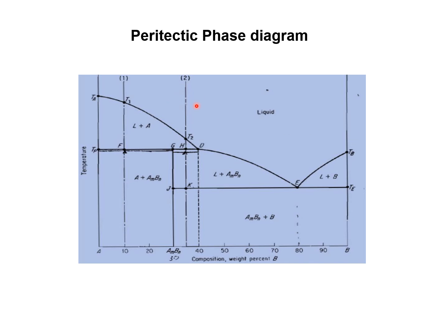Here this region is entirely liquid. Coming to this left portion, liquid will be there plus solid grains. Here the A percentage is very high on this side. Once it crosses this line, called the peritectic temperature, the entire liquid is converted into solid, plus A solid grains. That is called A plus compound AmBn.